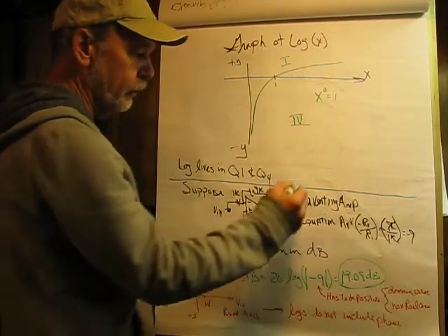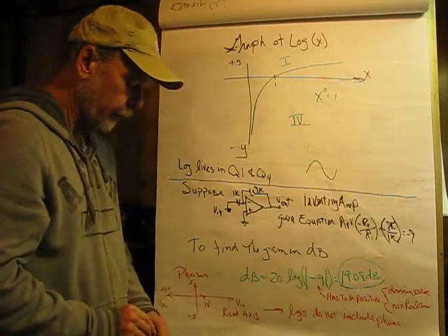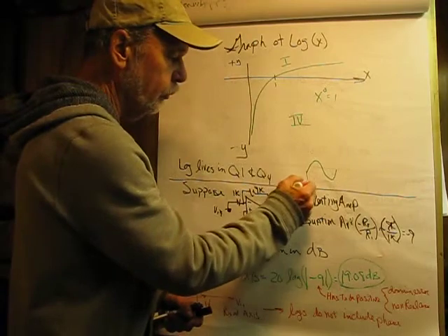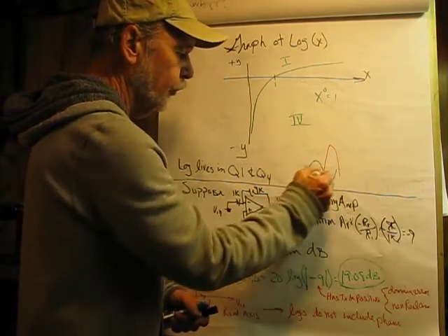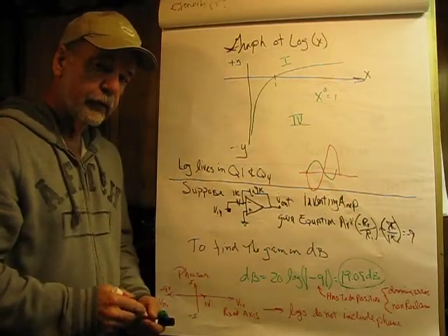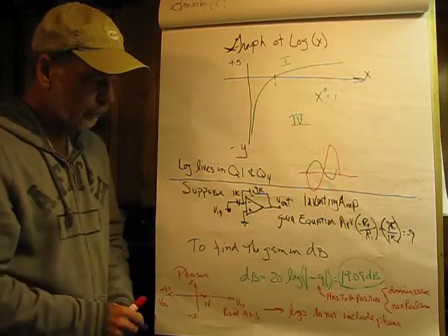Now what that basically means is that our input signal would be of this polarity, and our output signal would be 180 degrees, this polarity, and let me draw a line through that. So all the negative means is that the output phase is reversed by 180 degrees.